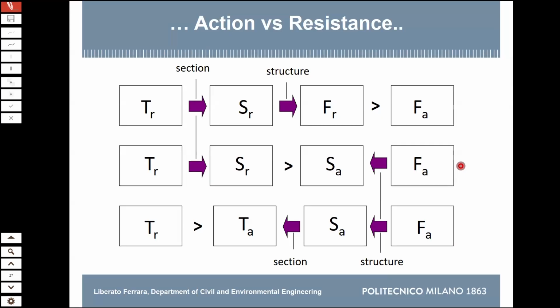You have your loads, draw the diagrams of force, and so on. So these are the general steps on the action side. Then the characteristic of your cross section: you use your section models, draw the distribution, and you have the maximum tensile and compressive action, which depending on whether maximum or minimum must be lower than the strength of the material.